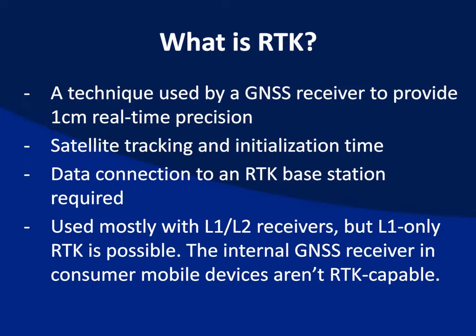But when you get into areas where you lose initialization, maybe several times a day or even several times an hour, I'm having to wait 3 or 4 or 5 minutes to get the fixed solution back for centimeter accuracy. That is just too long. So L1 RTK is viable in some applications, but you've got to be careful to make sure it really fits that particular application. I guess the value is that companies market their L1 RTK systems as a much cheaper alternative to L1/L2 receivers.